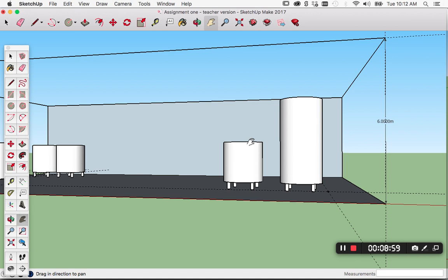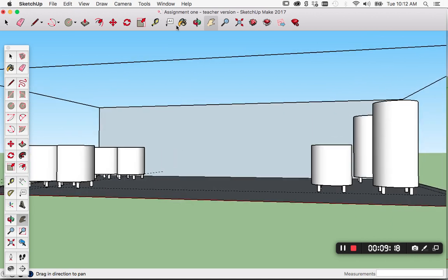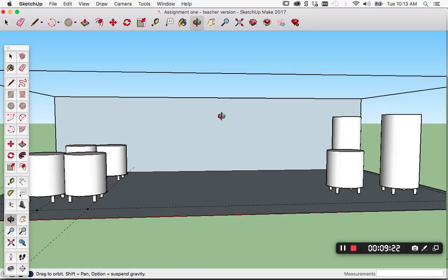And then we start pumping the second tank in, it begins filling up here, and this one going down here. So the maximum static head will be when this one's empty and this one's full, and that's 4 meters difference. So again, the static head will be 4 meters. So no matter what we do in this transfer, the maximum static head will be 4 meters.